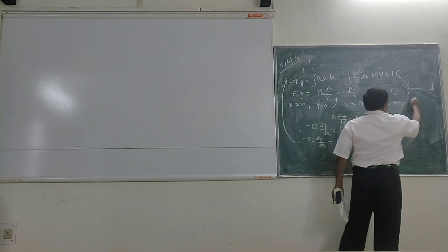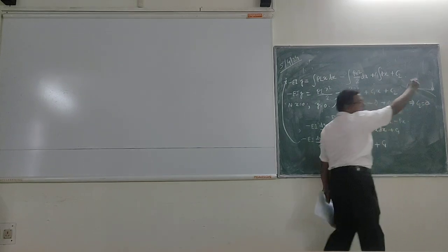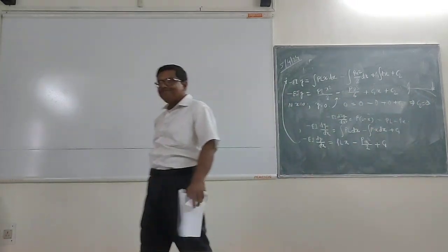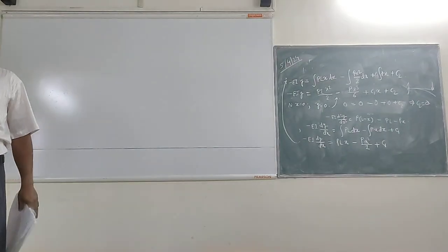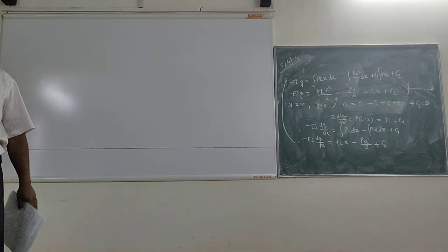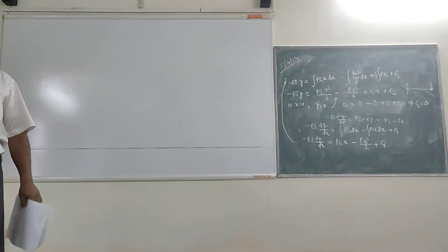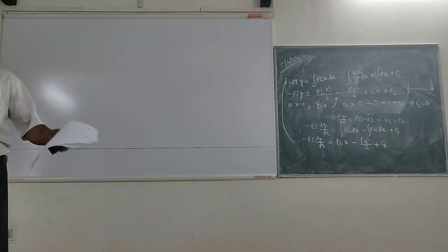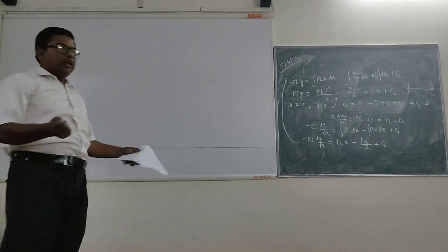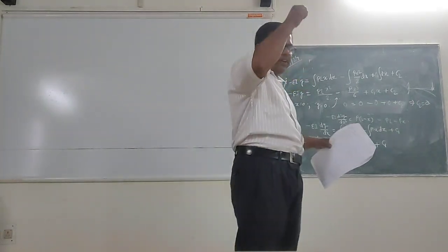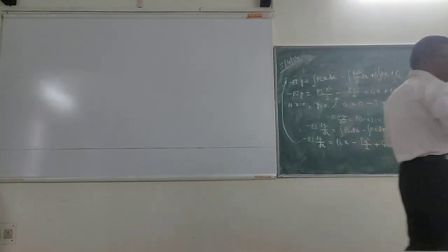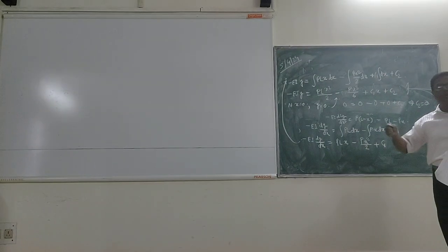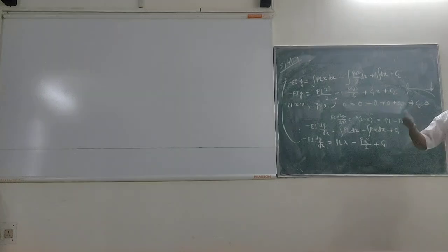So what will be my value of C2? It will become equal to 0. Have you understood? So C2 is becoming equal to 0. What I have done is only put back the boundary condition at x equal to 0, because it is a fixed support, so at x equal to 0 the deflection y will be equal to 0.